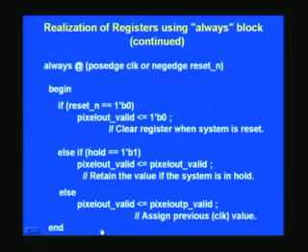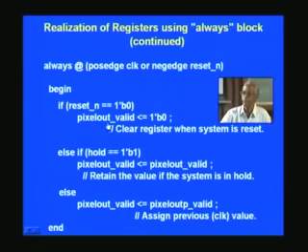And here once again, what we have seen is, when reset is asserted, this pixel out is the actual signal that we want. Earlier it was pixel out P, indicating the prior signal for this. This is the actual signal that we want as a delayed signal, but the actual signal was already pre-computed in the earlier cycle.